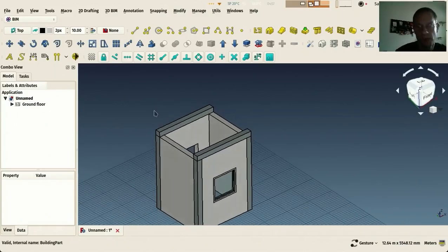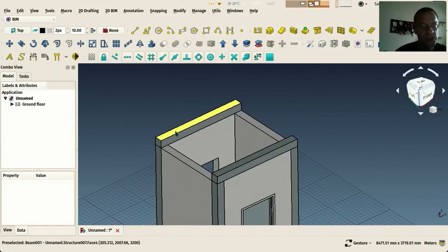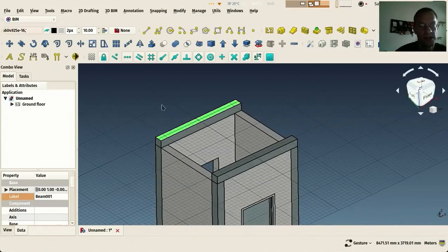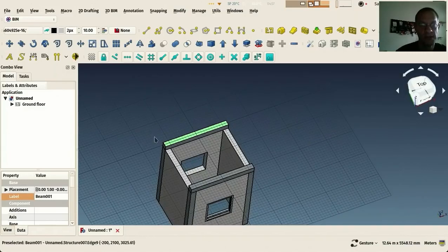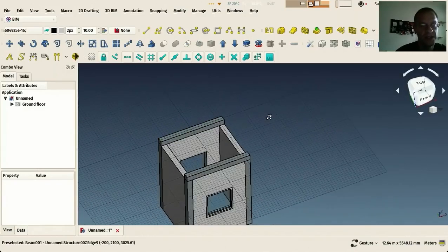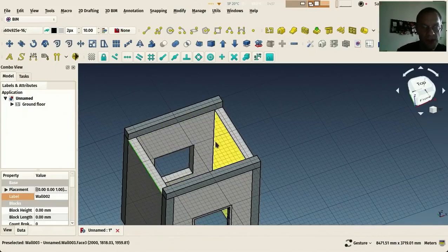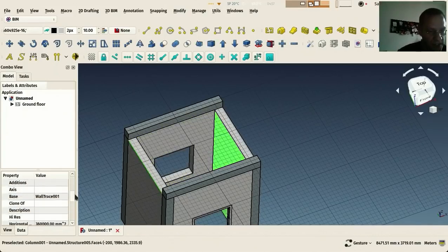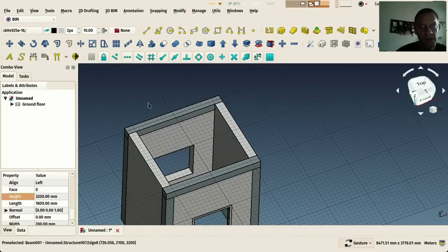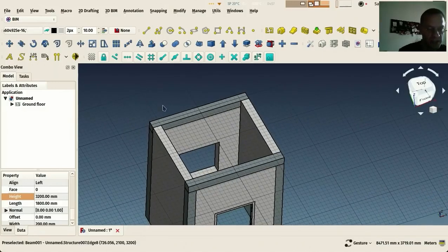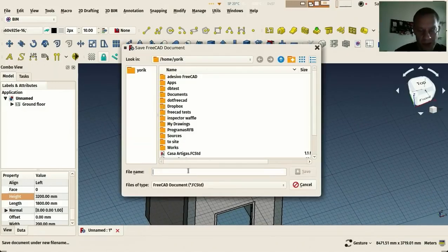So this works quite simply actually. We'll do just the same. I will place my working plane here, and let's add, for example, a slab here. We could make these two walls a little bit higher, right? This is better. Save your file at some point.